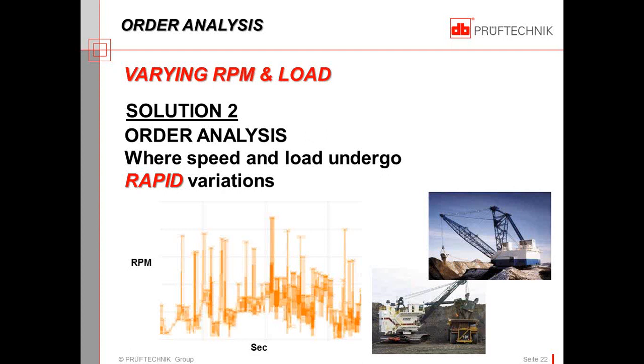And a year or so ago, I gave a paper on monitoring machines in the mining industry, and one of the solutions, apart from order analysis, that we recommended was we simply run the machine during a PM period and run it steady state. Now, under no load, this is probably not going to be representative of the vibration that we would have when the machine is operating.